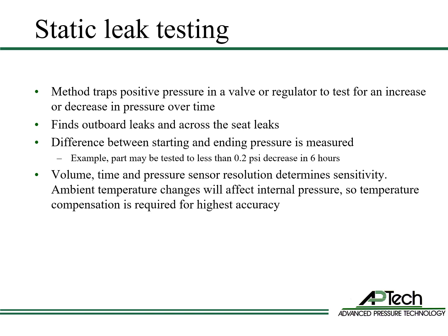For example, a part may be tested to less than 0.2 psi decrease in pressure over 6 hours. The trap volume, test time, and pressure sensor resolution determines the static leak test sensitivity. Ambient temperatures will have an effect on internal pressure, so temperature compensation is required for the highest accuracy.